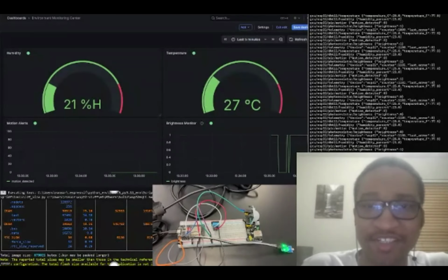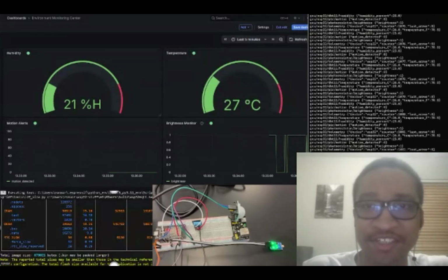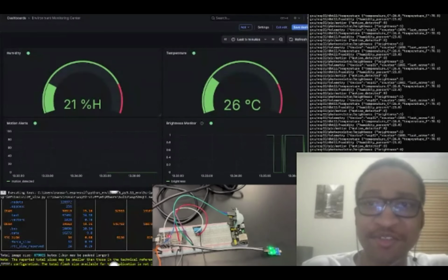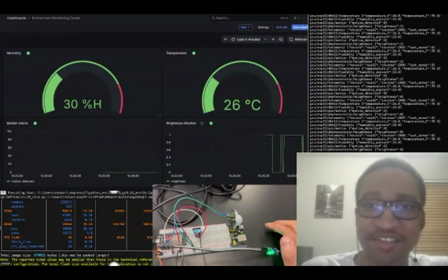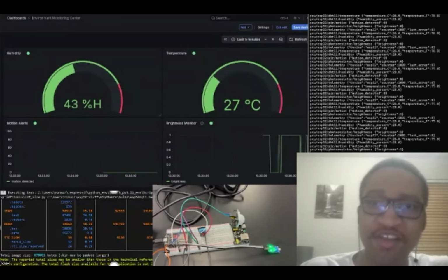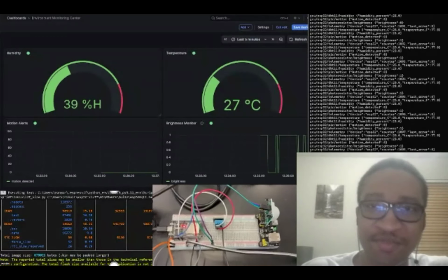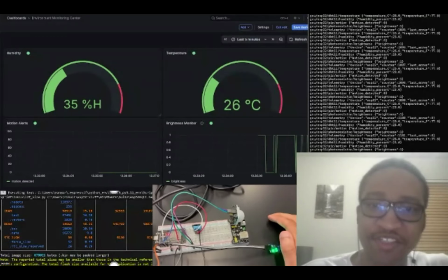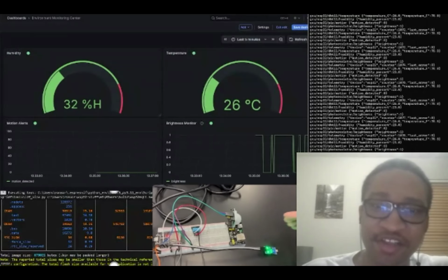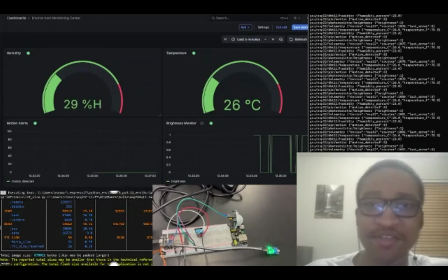So in our implementation, we now have two new topics for the motion detection and the brightness level detection. As you can see in the terminal, data is streamed in on the motion and brightness topics respectively. And the brightness is just a simple binary value of 1 or 0 depending on whether the light threshold is met. Covering the photoresistor as shown in the video will cause brightness to go off, and letting it be uncovered again will then cause the brightness signal to be raised to 1.